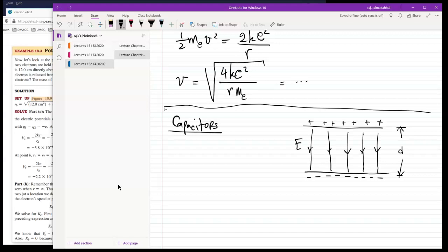And we said that there is a voltage involved here, where the voltage is maximum on the positive plate, and it is 0 at the negative plate. So in other words, let's say the voltage is 9 volt. So it's going to be 9 volt here. Then as you go down here, it decreases linearly. Why linearly? Because we said voltage is equal to E d. So as you can see here, the voltage is a function of the linear displacement.